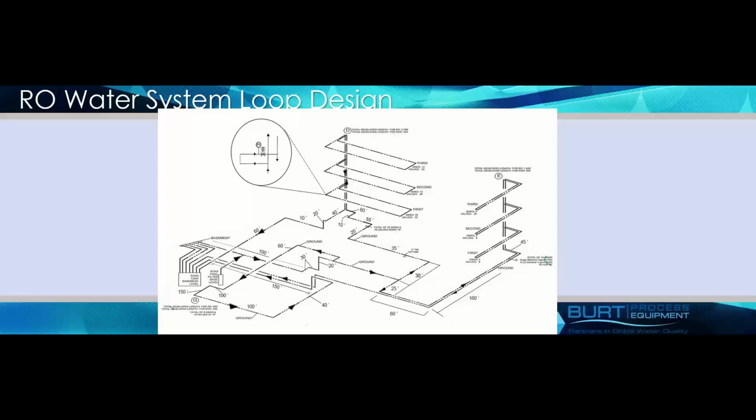You generally want 3 to 6 feet per second of actual flow running through your loop at any given time, even during a period of high use. So while you're looking at your various fixtures, you may only see an actual usage of, say, 40 or 45 GPM, your loop will run closer to 60 to 65 GPM at that point.